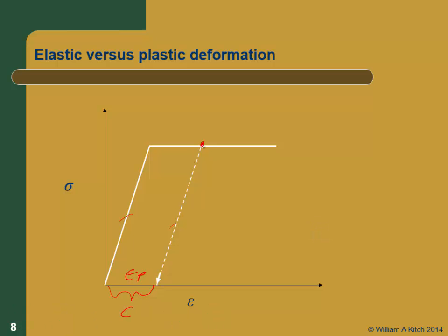And what about, now, the peak strain we had was right here, right? That was the maximum strain we had. So if I divide this up, I'm going to be smart this time, put it up here. What kind of strain is this? That was recovered strain, right? So that's actually the elastic part of this strain. That was the amount that was recovered. And by the way, this right here will be the same as that if those two lines are parallel. Okay?